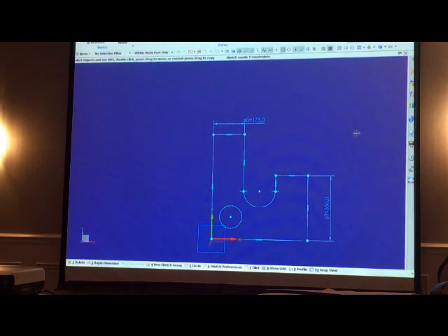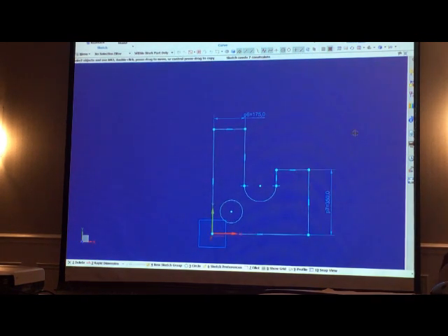Or you can just use the scalable group as a variable for changing the scale of something that you might have as part of your part design. I have some feature that is controllable just by expression, scale only. Or I could use it like this. I get to a certain point and say, oh gee, I wish that thing was 50% bigger. How am I going to change every single object in there to make it 50% bigger? Okay, make it a scalable group, make it 50% bigger, and unscale it. And so you can use it as a tool for that.